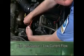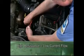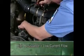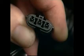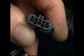As we've seen, excessive resistance will cause a reduced current flow through the circuit. Where the resistance is extreme, no current will flow. Excessive resistance will cause lamps to glow dimly or cause electric motors to turn slowly. Excessive resistance is usually due to corrosion on connectors or terminals in the connectors that are loose.